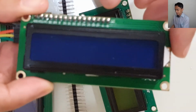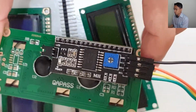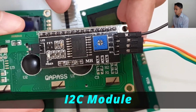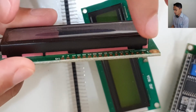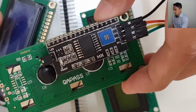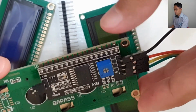but instead I will use this LCD. It's the same LCD, as you can see, nothing different, but the only difference is that I use it with what we call the I2C module. So let's say you already bought this LCD which is not soldered yet, you can buy this I2C module here, and then solder it onto this LCD, and just follow this.